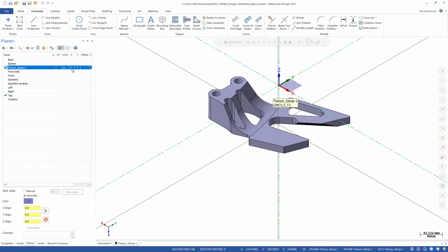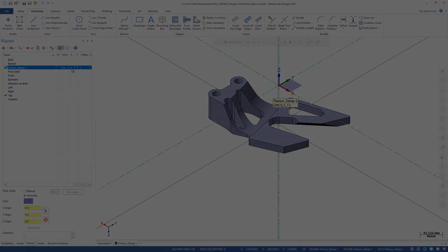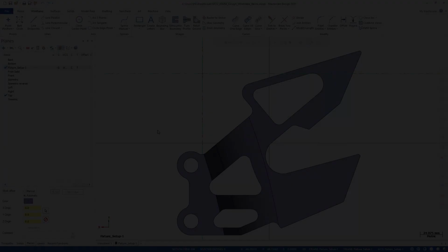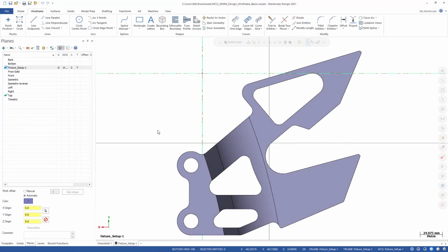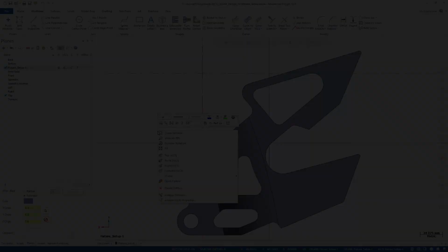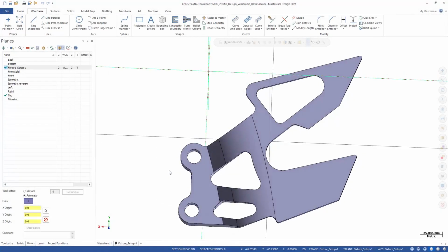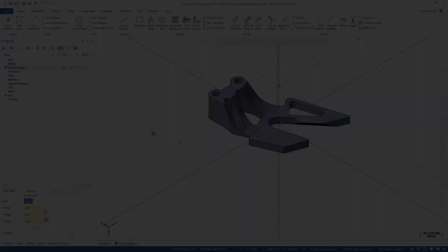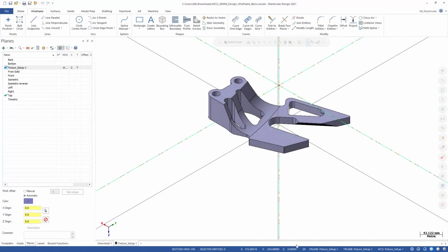In other words, this is a plane I'm drawing on, and if we look at it from the top view, we're looking directly at our plane. The question now is, at what depth are we drawing? I'll switch back to isometric to ensure that I'm at the proper depth. To do that, I'll make sure that I'm set to 2D in my construction mode, which limits my drawing onto a two-dimensional plane.